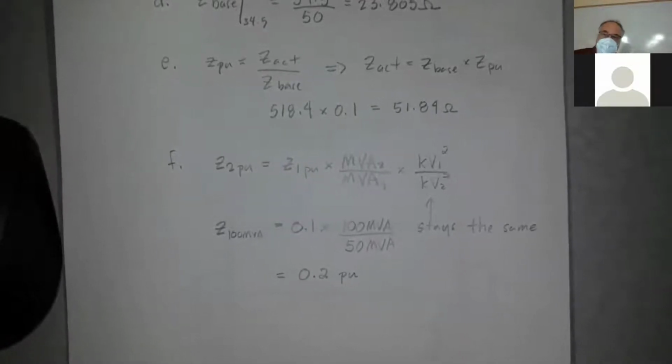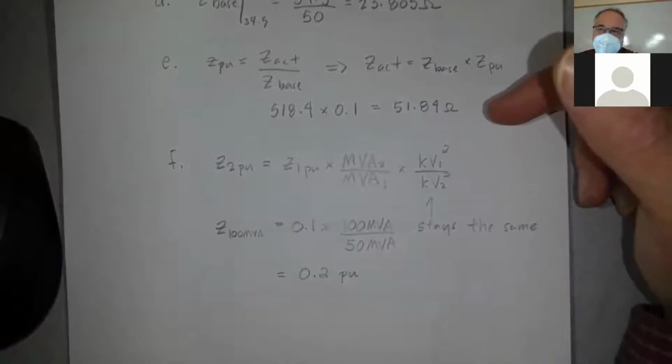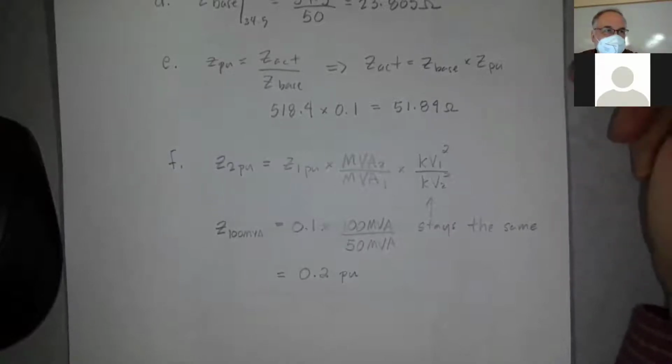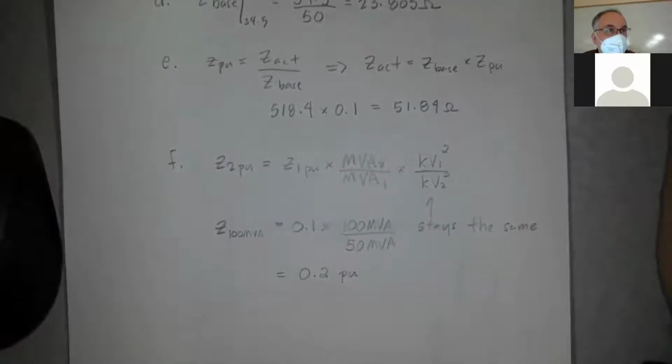So if the system map that we have is 100 MVA base, and we're just adding this one transformer to it, it wouldn't make sense to change everything else in the system to 50 MVA. We just need to change that one transformer to 100 MVA, okay? And the 161 kV for the 161 kV system, well, that should be the same. And the 34.5 for the 34.5 kV system should be the same. So we're not changing the voltages, okay?